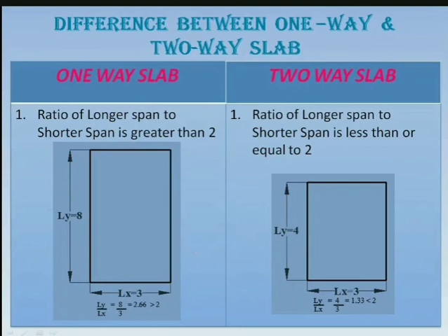Then, this point again, if you are having a pen or pencil, note it down. When we design the structure practically, for a residential building and all, many times what happens is we have rooms of size, say, 10 feet by 10 feet or 10 feet by 8 feet. So 10 feet by 8 feet goes as 3.1 meters by, say, 2.7 meters. So 3 divided by 2.7 comes as less than 2, but we don't design a two-way slab there.